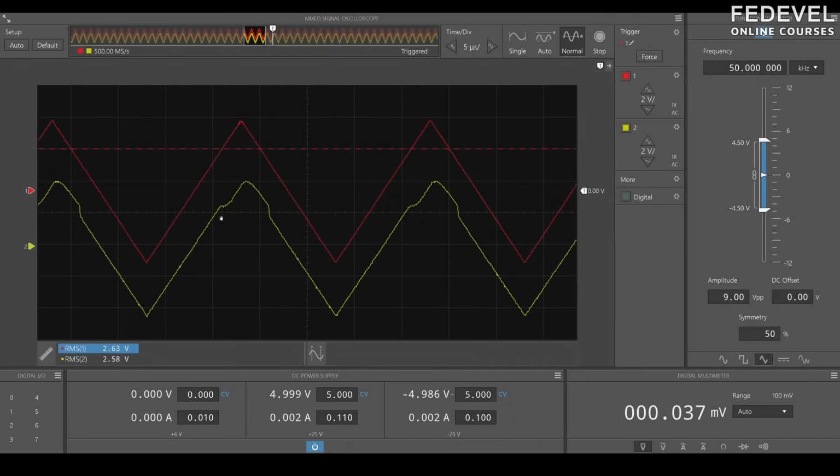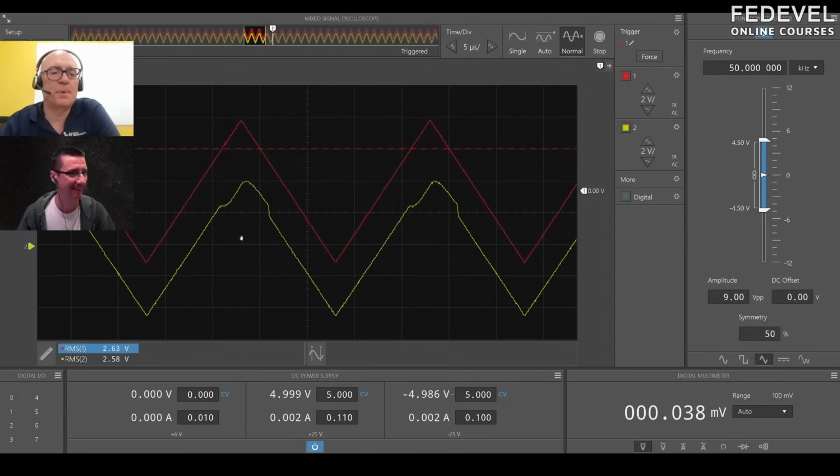The real device doesn't clip like the simulation does, but you can see that it's very distorted. It's really not functioning correctly. So the model in this case is showing a worse case than the reality, but bottom line is the part's really not functioning properly as a normal op amp would in this region where we're violating the common mode.